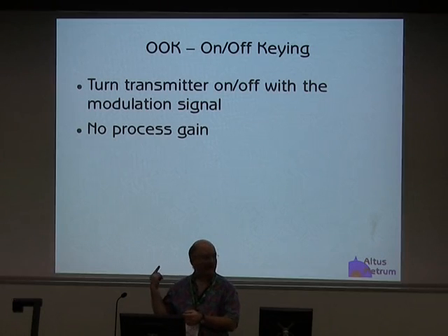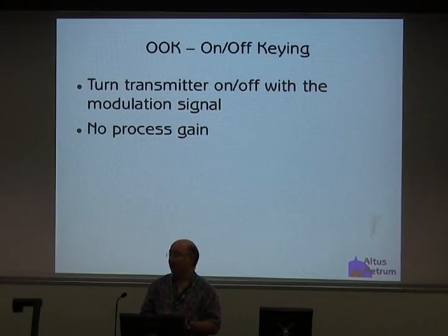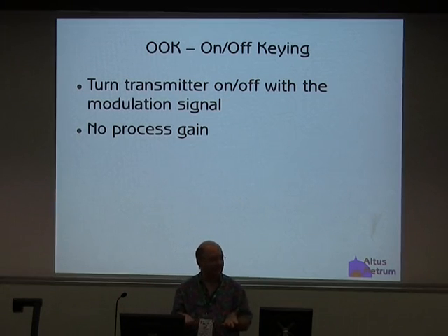Yeah, moon bounce. Yeah, okay. And that uses on-off keying, and of course it's lovely because you have a very low data rate and a really simple transmitter. The problem, of course, is that you have a very broad spectrum because you're keying a transmitter on and off, and you get no process gain at all. But in a weak signal environment in the FM world, you don't get any process gain anyhow.